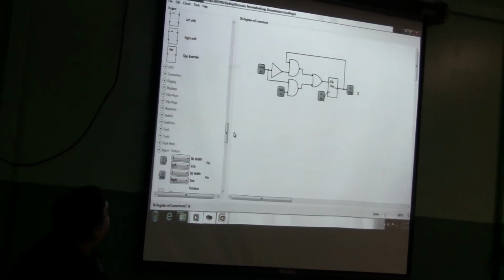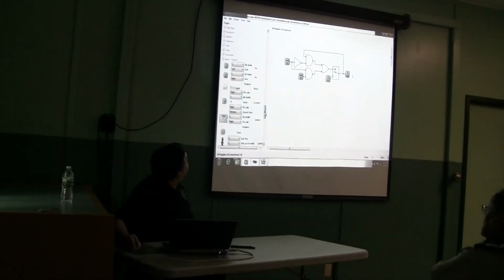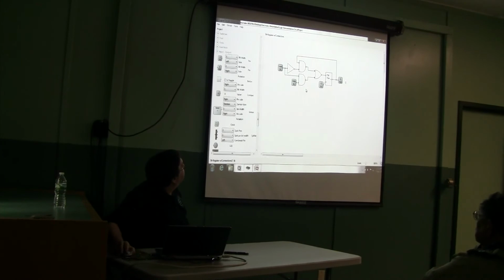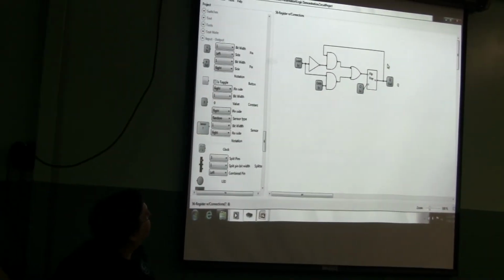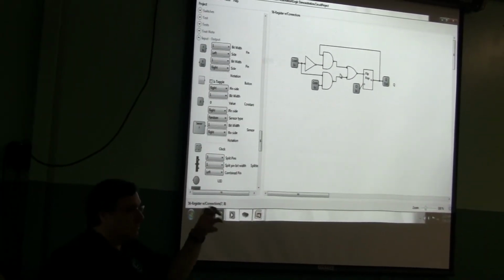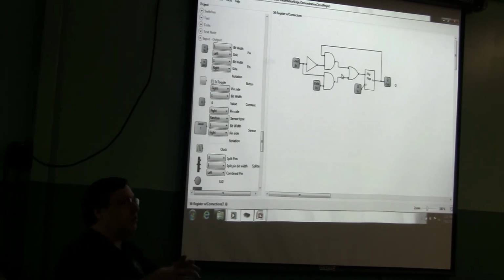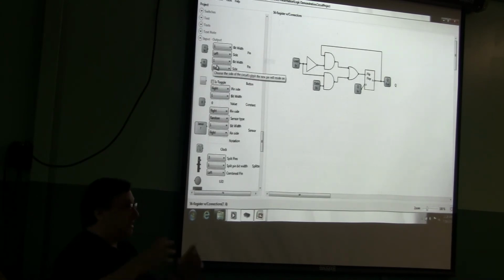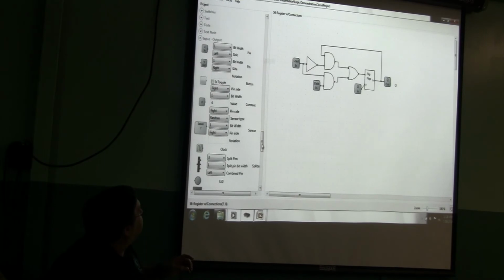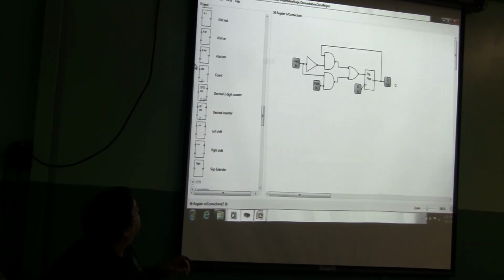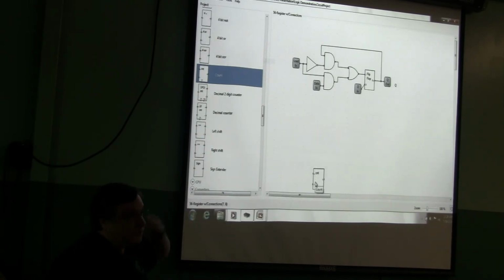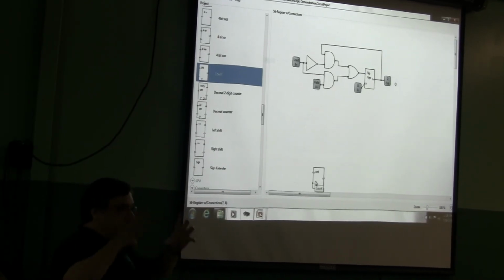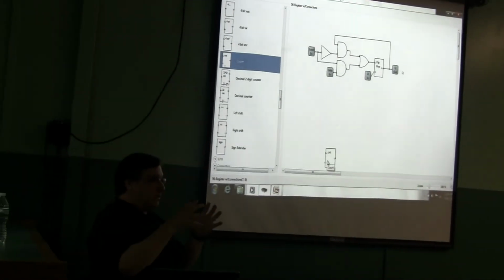You have input-output devices. So let's say I want to build some gates here into a circuit that I want to use elsewhere. I can tag them with these input notations and output notations, and that will create this little box with these little connections on it. Then I can drag this and use it and wire up stuff to it.